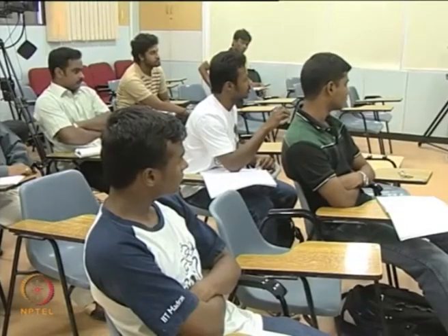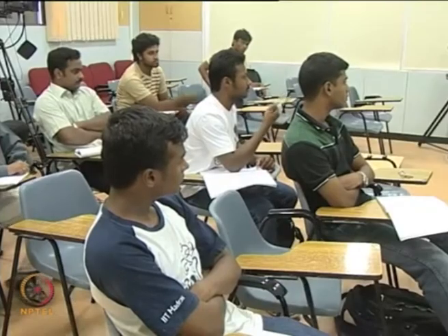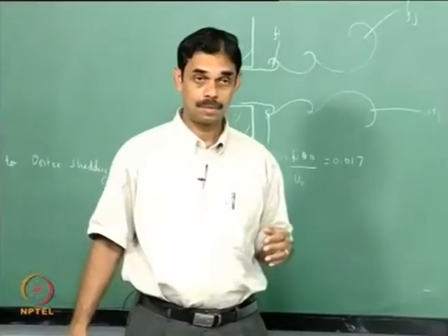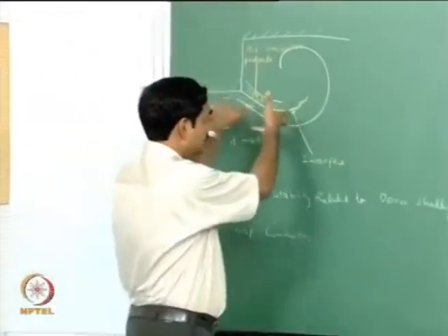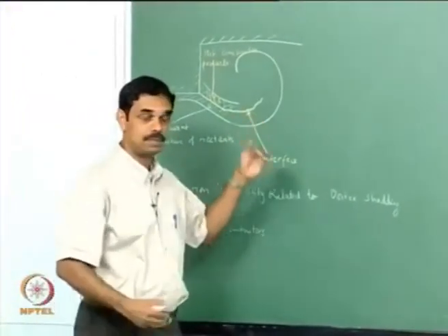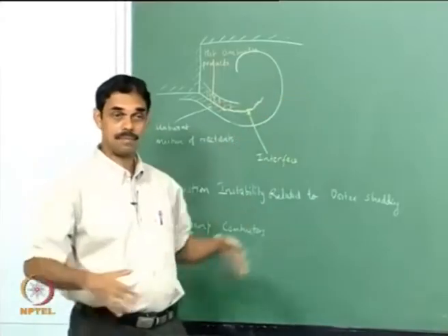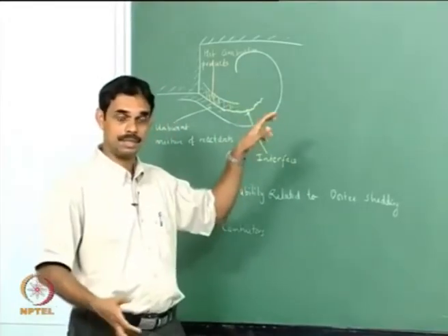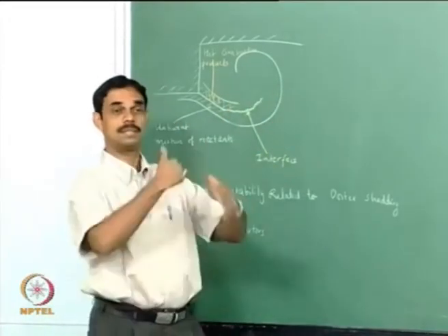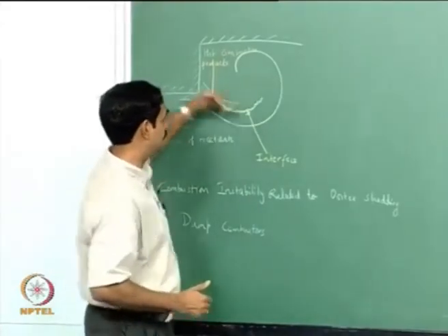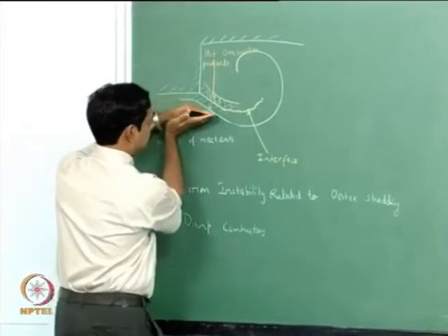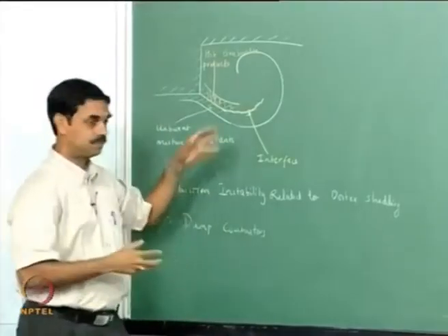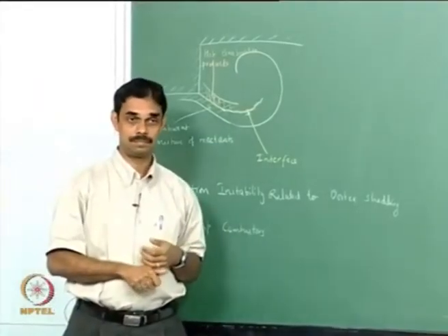So if that is sufficiently far from this instability, then it should not be periodic. Because the whole thing is starting with periodic. If you don't have the big scale and if you have small scale turbulence right from the beginning, then you will have continuous combustion, but it does not come right from the beginning. The fine scale turbulence is happening as the vortices roll up. So initially this is not a steady picture, it just comes like this, then rolls up. Until it starts rolling up, the fine scale turbulence will be minimal. That is what I understand.